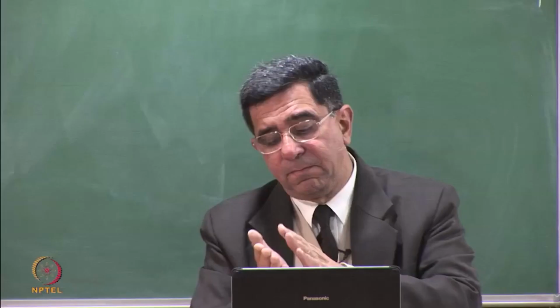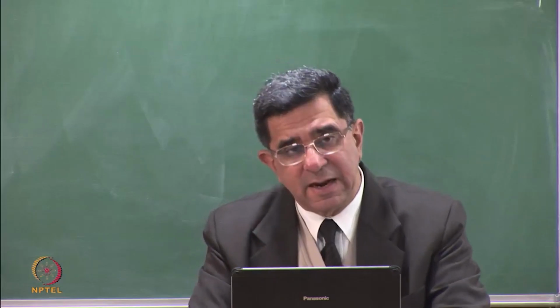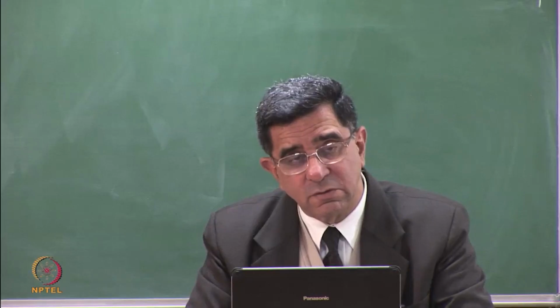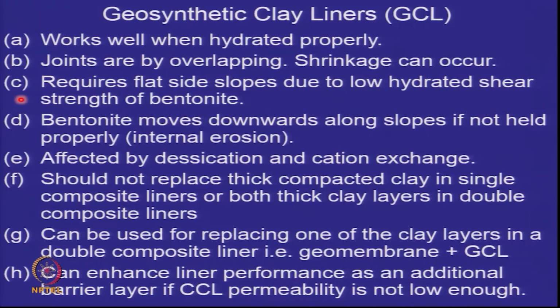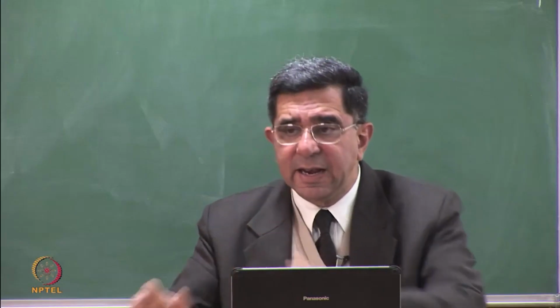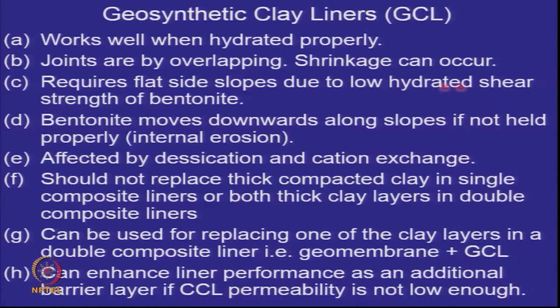Because of the bentonite, when it hydrates, its strength is very low. It's like a clay powder. So when you put it on the sides, it can have a failure. So it requires flat side slopes due to the low hydrated shear strength of bentonite.